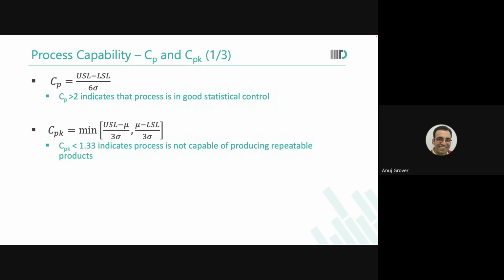When a new process is launched, for example, they introduce a 3 nanometer process or a 7 nanometer process for the first time in your organization, the process capability is bad. Then you practice and you observe the spread, what is leading to this significant variation, and where my lot is centered. You start to tweak your process according to the machines on which you are processing. And then gradually you bring the process under control.